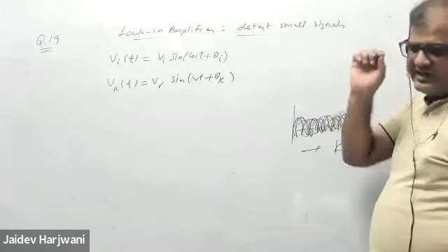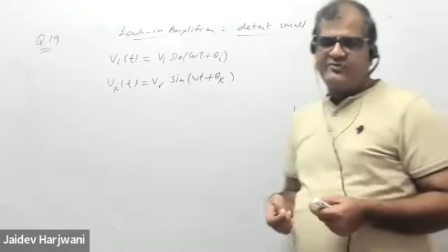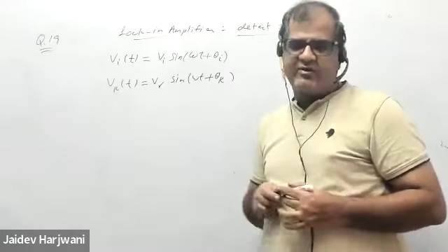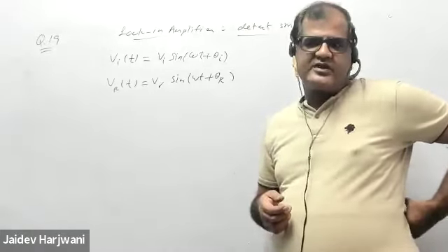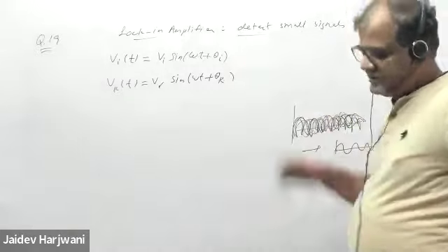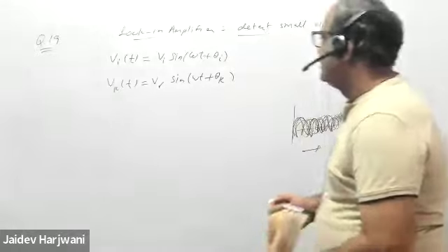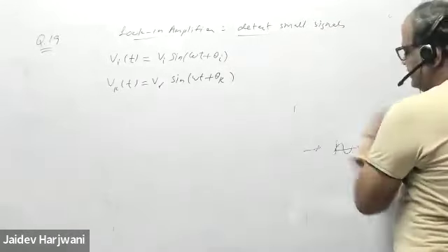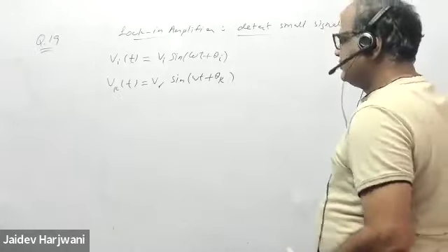That lock-in amplifier can tell you. While measuring, sometimes noise is very high, especially when we are doing measurements in nanoelectronics. Your output voltage or signal will be in microvolts and nanovolts, so that experiment is done using a lock-in amplifier. So now, what does the lock-in amplifier do?